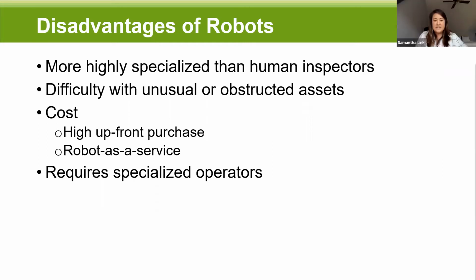Great. And then is there any work on an eddy current probe for looking for cracks? Yeah, we'll talk a little bit about that in the future. It's something that we're looking at, at least with our robot. We have the ability to attach different sensors to our robot. So currently we can put UT thickness reading sensors and then also magnetic induction sensors on it. Eddy current is something that's been discussed for the future, for sure.